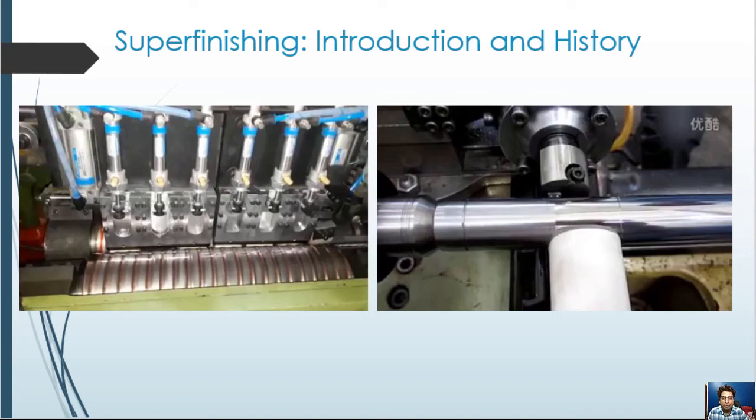When the cars were put into service, the depressions caused excessive noise. It was found that brinelling could be eliminated by removing the fuzz generated in the grinding of the load carrying surfaces of the bearing. The development of the fuzz removing process led to the development of the super finishing process, and in early 1934, the process of superfinishing was first conceived by D.A. Wallis of Chrysler Corporation.